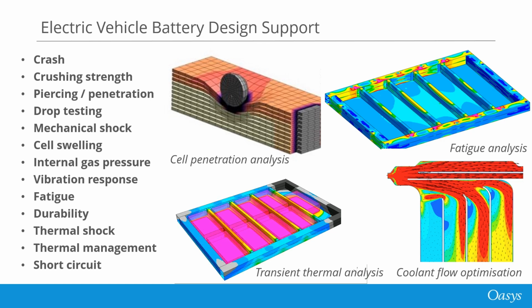So at its sort of heart, and originally LS-DYNA was and still is a non-linear structural time explicit finite element solver code, and it's very, very good at dealing with highly non-linear or transient problems. So situations where plastic deformation and yielding is happening, for example, in a structural system, which is why it's so very good at dealing with crash and safety cases in the automotive industry.